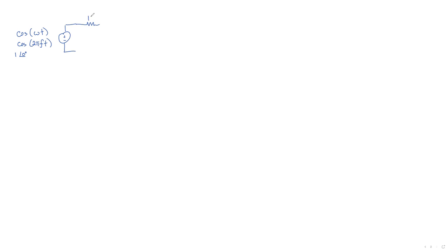And we're going to make a voltage divider out of this. Here's a 1 kilohm resistor up here, and it's going to be in series with a 160 nanofarad capacitor. And we're interested in reading what the voltage is across that capacitor.